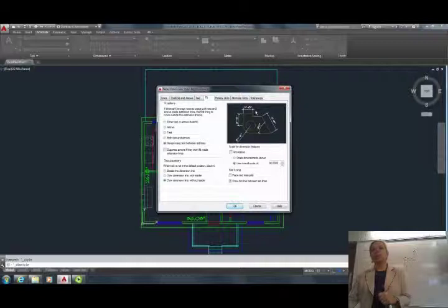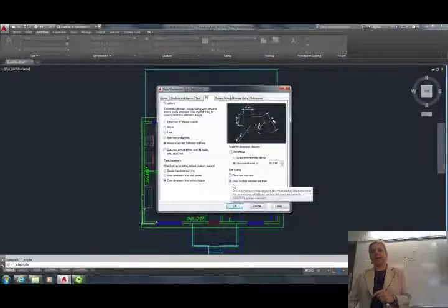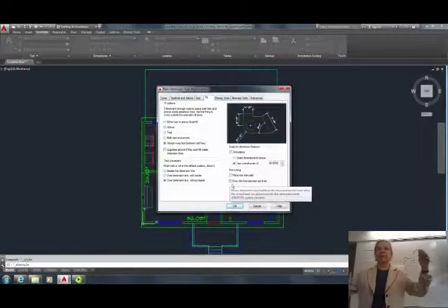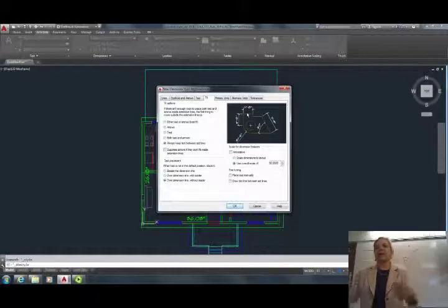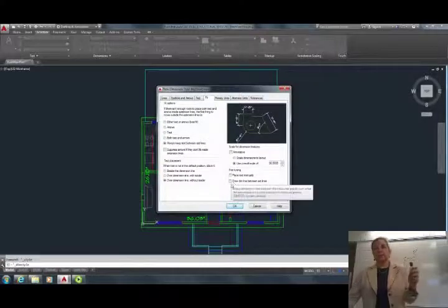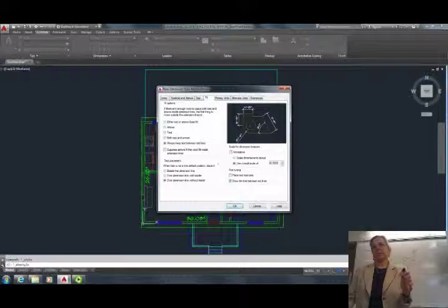We also always want to draw line between extension lines, okay? Look what happens if this is off, and that again relates back to mechanical drawings. Mechanical people have the line broken to show the actual dimension, so it would look ridiculous if the dimension line goes through the text, but we are always above, and the drafting standard for us is always draw dimension line between extension lines.